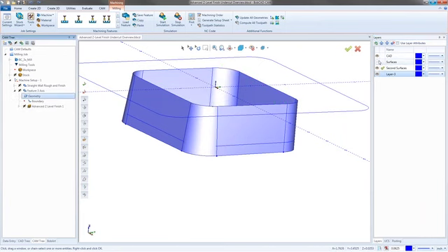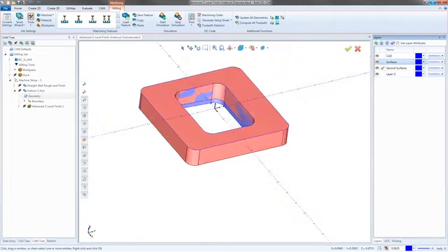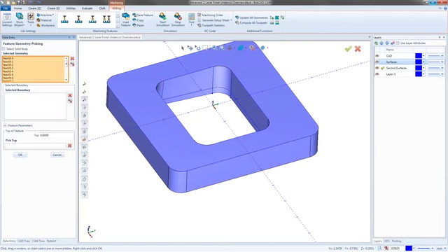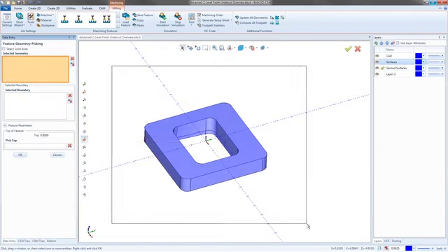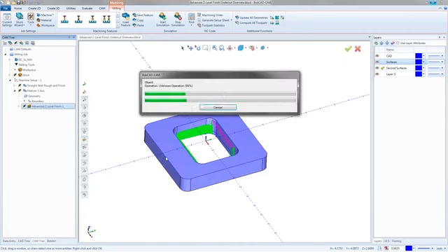So what I do with this is I turn on all my solid models now, just like this. Then I right click on the geometry and say, let's remove the old stuff. Then I reselect the new, pick everything together, and hit OK. Now I can compute my toolpath, and it's going to allow that tool to go lower because it sees the geometry and it can reference off of that geometry down that.